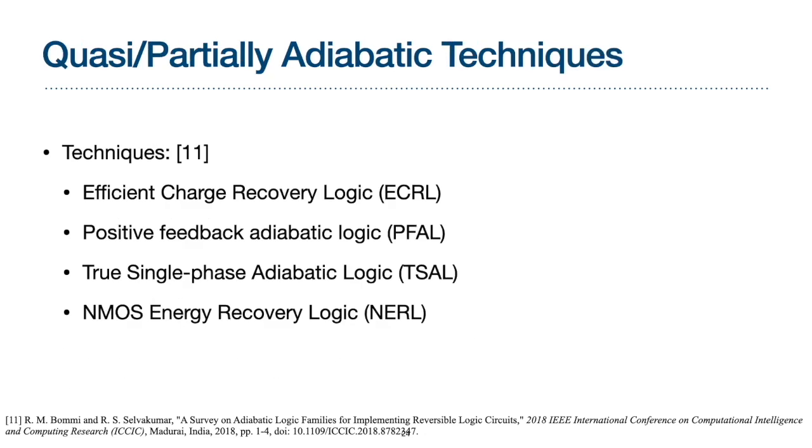So, with quasi and partially adiabatic techniques, there are a few primary ones, a couple of which we listed on the previous slide. These include the efficient charge recovery logic, ECRL, the positive feedback adiabatic logic, PFAL, the true single-phase adiabatic logic, or TSAL, and the NMOS energy recovery logic, NERL.